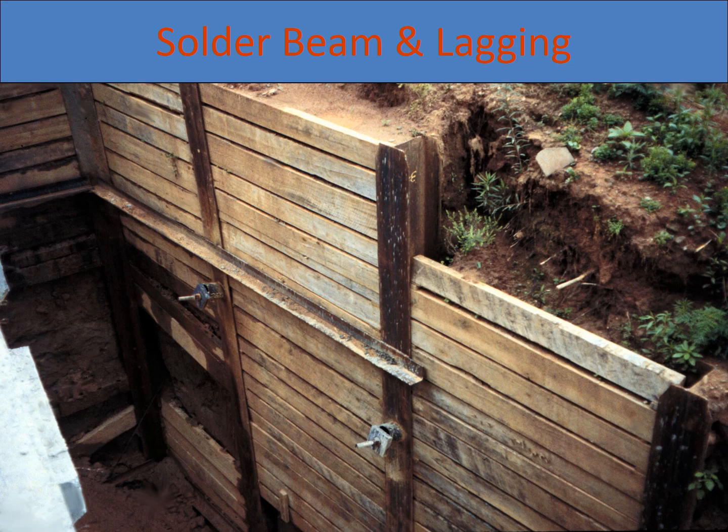So this is a technique known as soldier beam and lagging, and the soldier piles are the vertical structures made of H-beams. This is an earth retention technique that retains soil. The horizontal wood members are called lagging, and typically the H-piles are driven at regular intervals along the planned excavation perimeter.